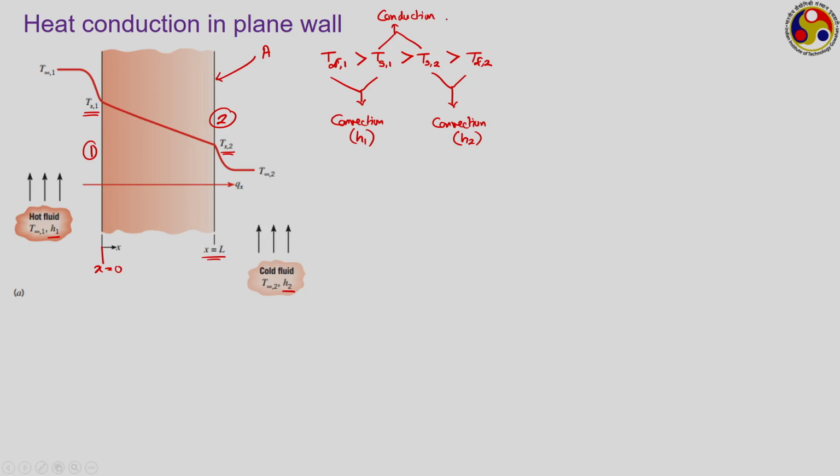So, we have considered A to be the area of the wall, and we are considering a thermal conductivity, say K, in this x direction. I am not putting any subscript x because we are talking again about 1D heat conduction. So, what are the conditions that we are imposing? Firstly, 1D heat conduction, secondly, steady state.